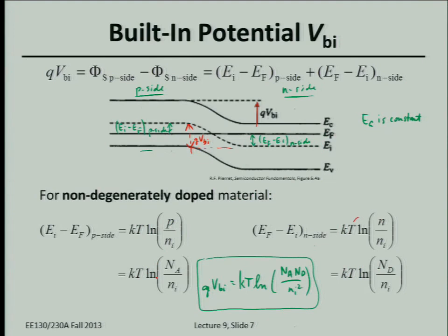Okay, so here's a PN junction diode at equilibrium. But if you shine light on it, so if you were to generate an electron-hole pair because of light absorption, you have a hole here, an electron here that's generated due to light. So the electron will want to drift to the right, and the hole will want to drift to the left, and they can flow out the metal contacts and generate current. I mean, so you can detect it. Your circuit can detect light shining, right? So that's a photodetector. If you want your photodetector to be more sensitive, then you want to generate more electron-hole pairs. So you want the depletion region to be wider, so more volume of light generation.